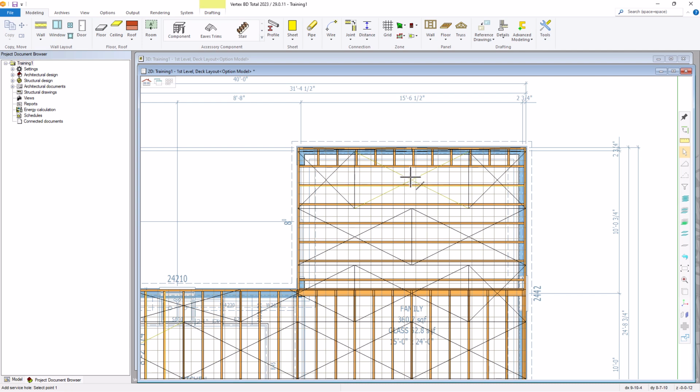Since we have a quantity of 3 holes at 12 inches apart, the line that we're drawing is the middle hole, and with holes offset at 12 inches on each side. I want to start at this point. Select the I key to lock it into vertical. Go all the way through this joist. The 3 holes are represented by the dashed line. So we have holes in the joist going along each one of these lines.